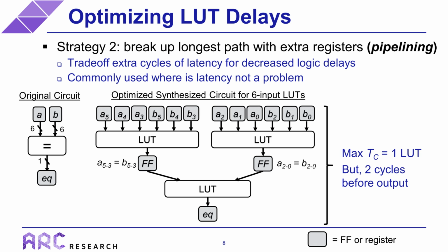However, now that we want to add registers in the middle of that logic, we might have to design the comparator in a counterintuitive way where the code explicitly divides up the logic based on how it would be placed into lookup tables, and then put registers on the outputs of each one of those lookup tables. So this is clearly not a productive way of designing. Fortunately, there is a way of automating this in many cases, which we will see on the next slide.